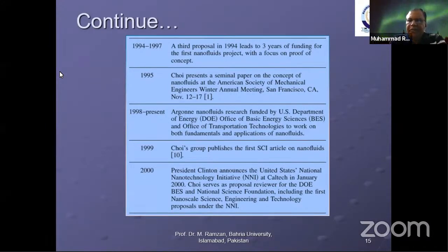In 1997, based on the concept of nanofluids, Argonne thermal scientists have developed an advanced cooling technology. The advanced cooling approach relies on many microchannels consisting of long, narrow slits only thousandths of an inch wide, and coolants containing nanometer-sized metallic particles. In other words, the innovative process employs microchannels filled with metallic nanoparticle-laden coolant to extract heat faster than the present technology. This advanced cooling approach provides more efficient cooling than any other cooling technology because the microchannels increase the effective heat transfer area and the metallic nanoparticles increase the effective thermal conductivity of the fluids.